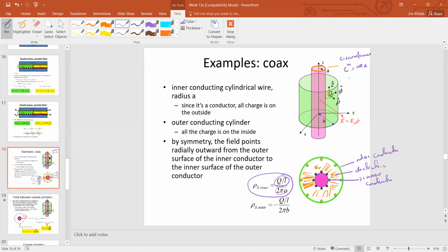Okay, the total surface area of the inner conductor is equal to, suppose A, which equals the circumference multiplied by the length of the conductor. Is that true? 2 pi a dot L. Okay, and say we have Q charges. Q is the charge on the surface.